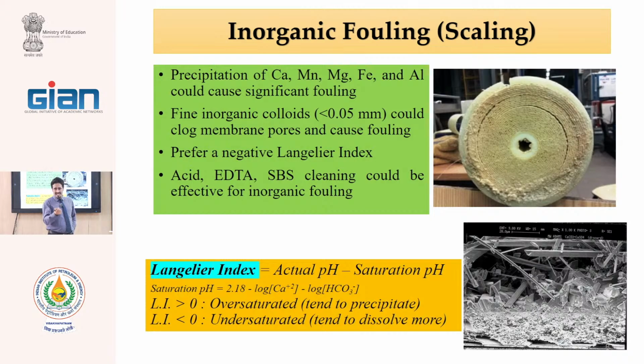When we say cleaning, we use a cleaning agent, but when we say washing, we use only water with mechanical cleaning, such as bubbles, okay? Usually every 6 months, we clean the RO and NF membranes with a cleaning agent, using a different agent based on the foulant type. For these crystals, which are inorganic compounds, we mostly use acid.